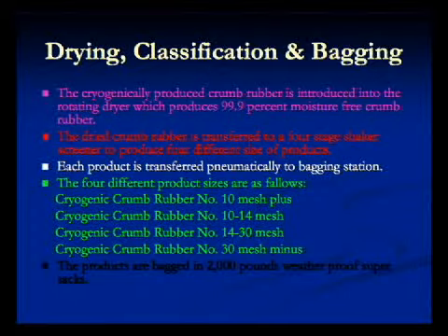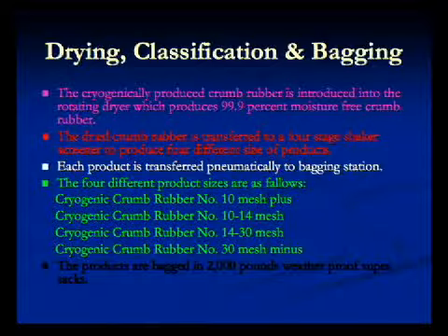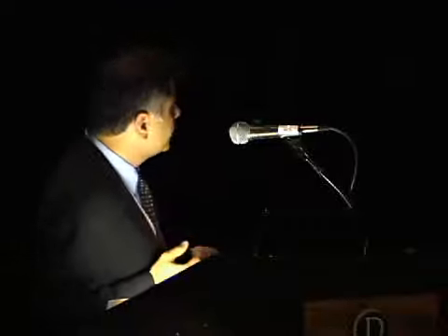You've got to remember, we took the chip, which was at room temperature, and froze it down to minus 290 degrees Fahrenheit. Within a matter of seconds, we bring it from minus 290 degrees Fahrenheit back to room temperature. So you're going to develop condensation, so you develop moisture in your rubber. So we need to go to a drying system. We dry the rubber in an actual dryer.